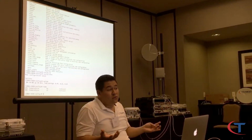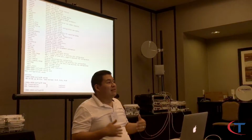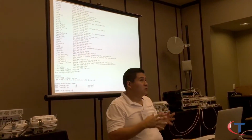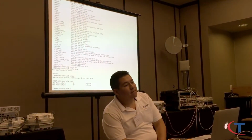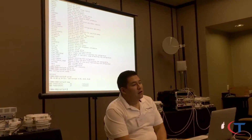I saw it was, to me, bone dry. I didn't switch the cable again because I didn't want to change it, but that's something for you guys to look at. I mean, IF cables are one of the most related problems in split systems. So just keep that in mind. Is there anything good? I mean, how do you really test it to make sure it's good? Just have a digital voltmeter reading of what it was when you installed it?